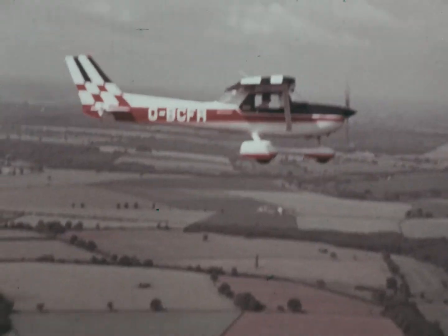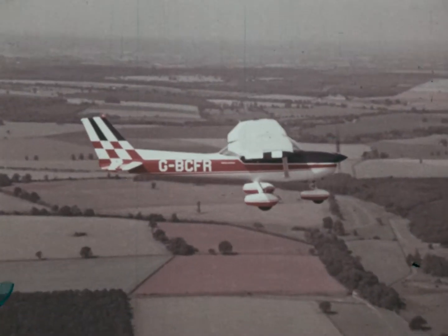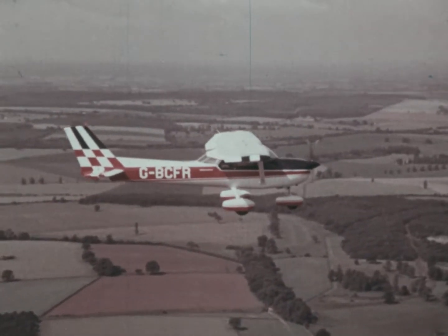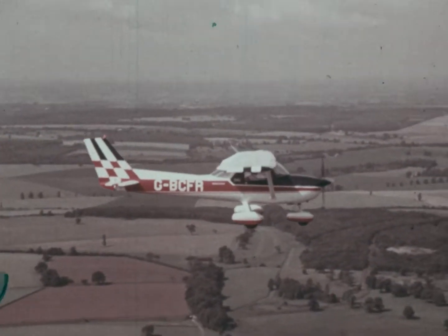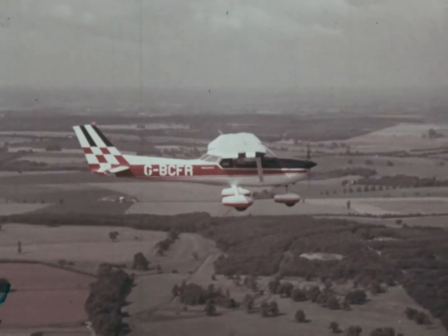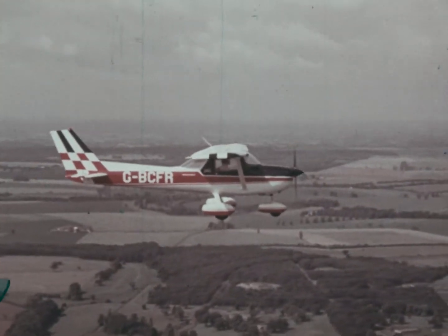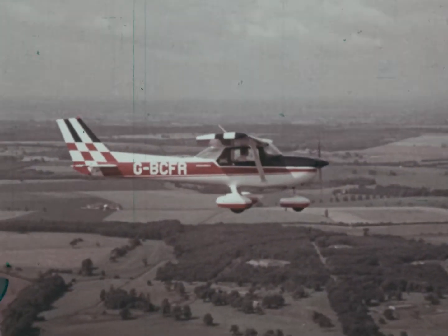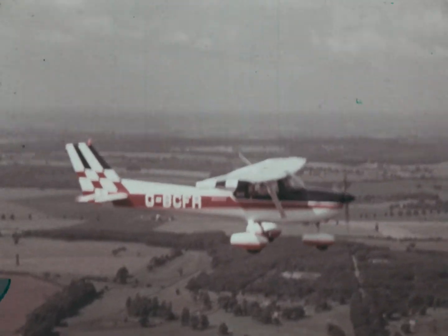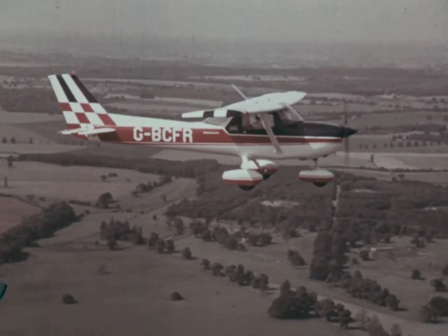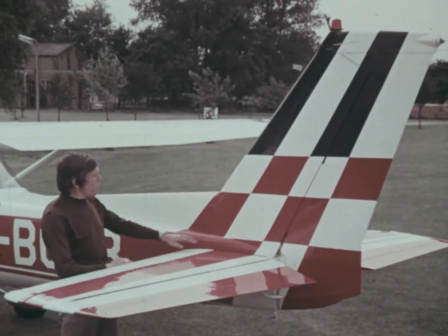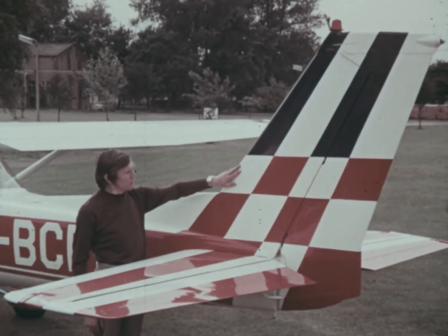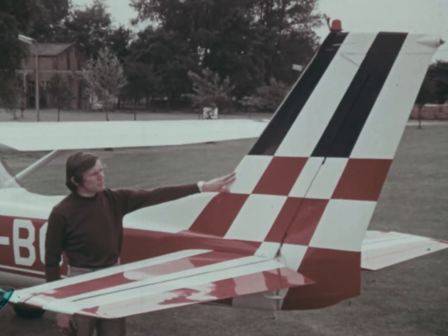Stability is a complex subject, but its basis lies in the plan form of the airplane and the arrangement of its flying surfaces. In the pitching and yawing planes, stability is assisted by the tail surfaces, exerting leverage along the arm provided by the fuselage. If we look at these tail surfaces, we find a horizontal tailplane and a vertical fin. Let's see how they help stability.